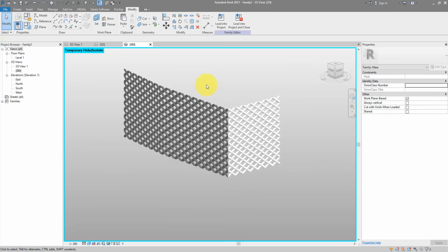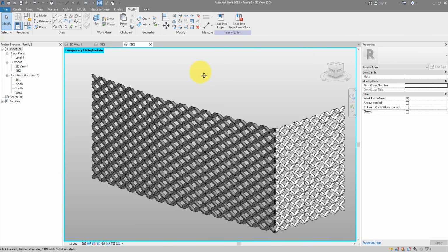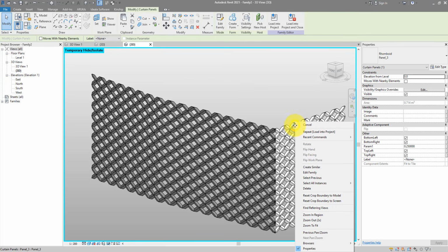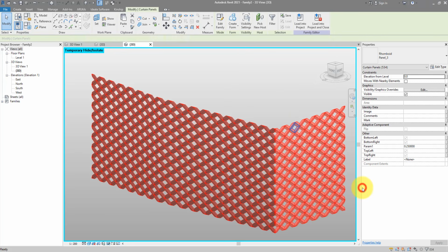Okay, that's done now for the whole system. As you can see, it was a bit manual, which is why some people prefer to do this kind of geometry in other programs like Grasshopper or Rhino. These are obviously a lot more powerful, but then they will have problems with translating that geometry back into Revit. In here, we have everything ready and of the same correct category, curtain panels, so at least for now, this is an acceptable compromise.